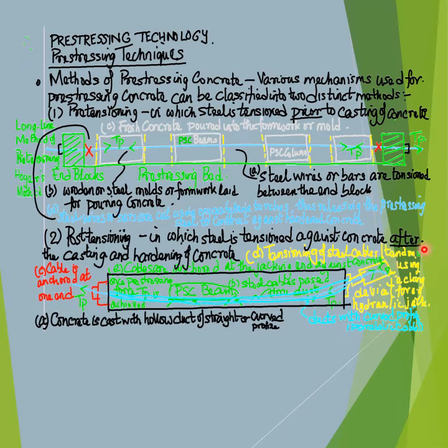Thus, tensioning the steel cable or the tendon at the jacking end using a jacking device, for example, a hydraulic or a pneumatic jack, generally a hydraulic jack, that tensions the steel cable at the jacking end against the anchor at the anchoring end as well as the concrete in the pre-stressed concrete specimen.